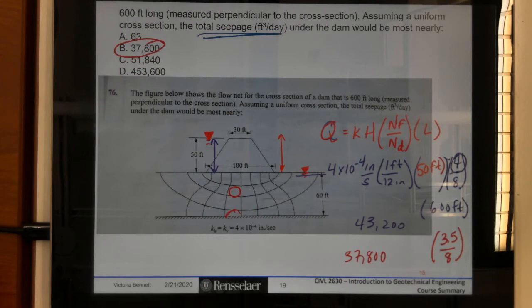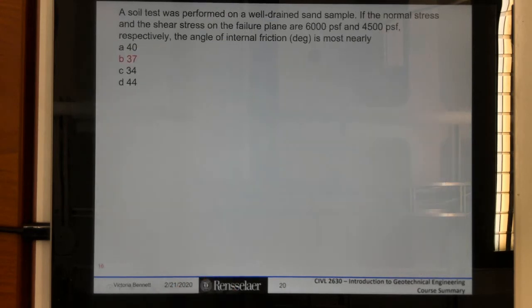So I don't know. Would they be that nitpicky about the flow net problems? I'm not sure, but I would say at least recognize that there is a little precedent for that. So when you're given one of those problems and you look at it, maybe don't just say, oh, I'm going to count immediately. Look at the size of those elements to see if it really is appropriate to just go with that.